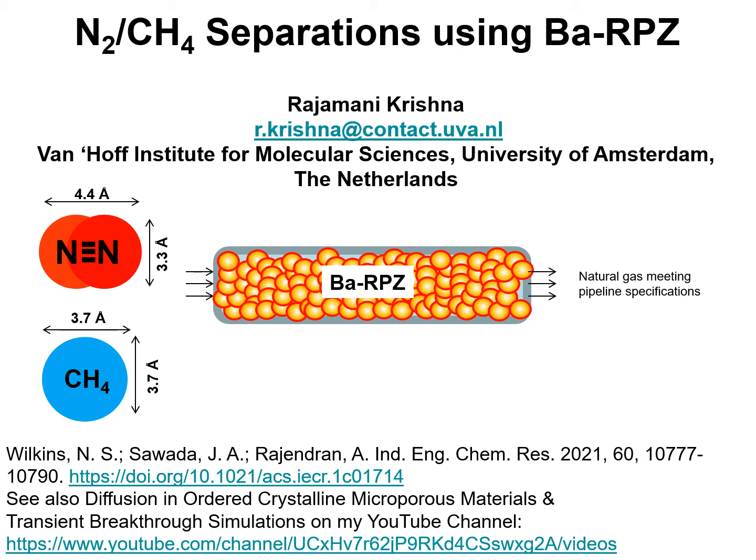It is desirable to use adsorbents in PSA units that are selective to nitrogen. For most known adsorbents, however, the adsorption selectivity favors methane due to its higher polarizability. One practical solution is to rely on diffusion selectivities by using microporous materials such as LTA4A zeolite and ETS4 that have constricted pore openings.